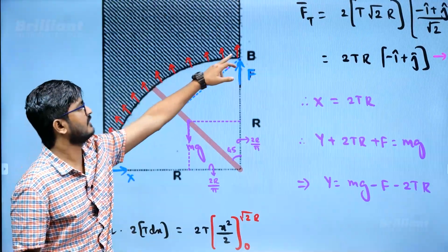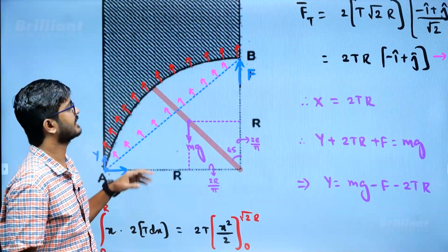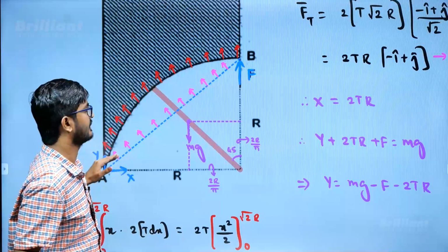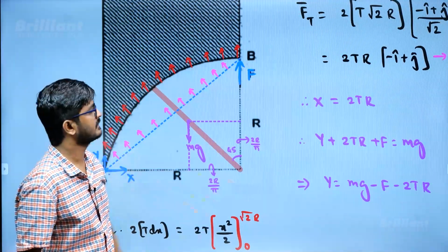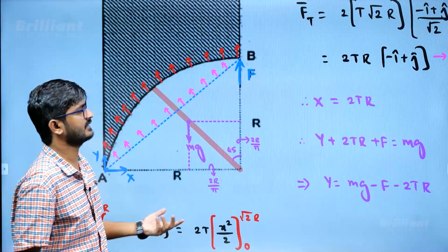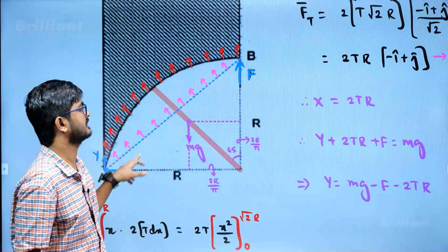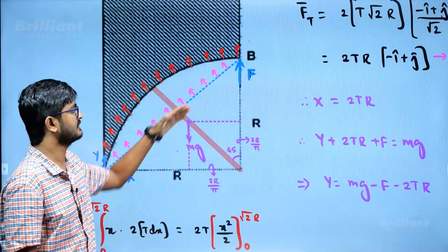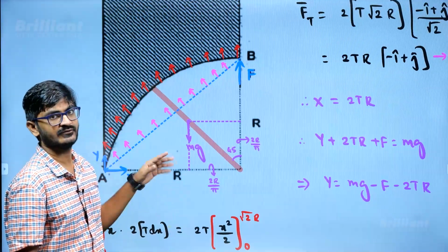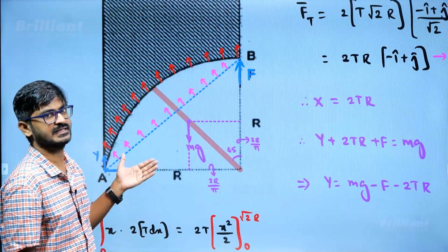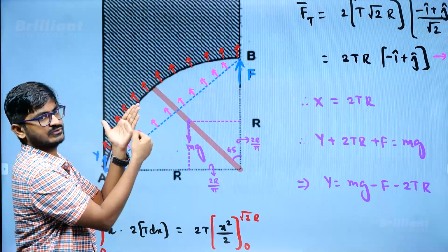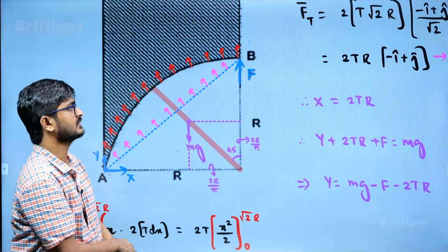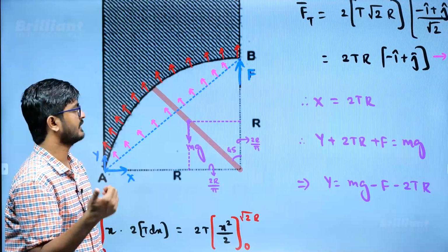Now, if I want to find the force, we have already seen that I can go with effective length. I can visualize it like instead of this one, there is an effective length, right? So if you want to find the surface tension force, that is surface tension times effective length, right? That is if one interface is there. But how many interfaces are there? When I am going from this side to this side, I will be going from air to soap film and soap film to air. So there are two interfaces. So there will be T into L two times, right?